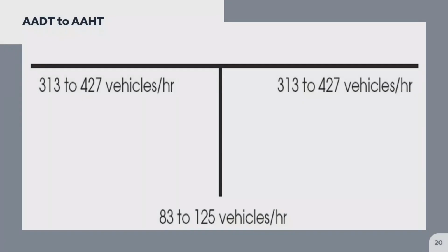The two-way annual average traffic on the arms can be taken by dividing the AADT by 24, which will produce the following values on the next figure. In this case, the AADT is translated into AAHT.